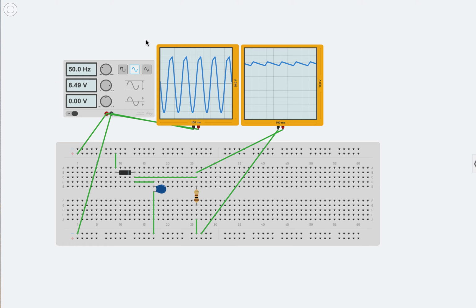So first off, we'll talk about task 1, where we can show that we're getting the DC voltage out and there's a ripple that is less than 2 volts, as shown here. The circuit works by taking the AC voltage in first, and it flows into the diode, where it only allows a positive voltage coming through.